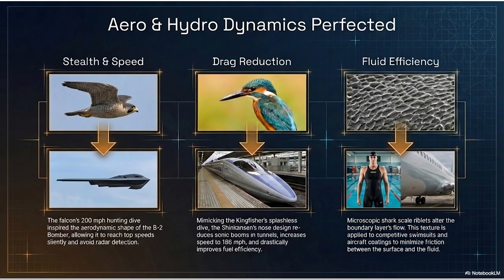And when that wall of high-pressure air finally burst out the exit of the tunnel, a literal sonic boom was a massive problem. The micropressure waves were so loud, they were terrifying residents living near the tunnel exits, waking people up in the middle of the night, and even threatening structural damage to the tunnels themselves. The engineers were completely stumped on how to solve it without significantly slowing the trains down, which completely defeats the purpose of a bullet train.